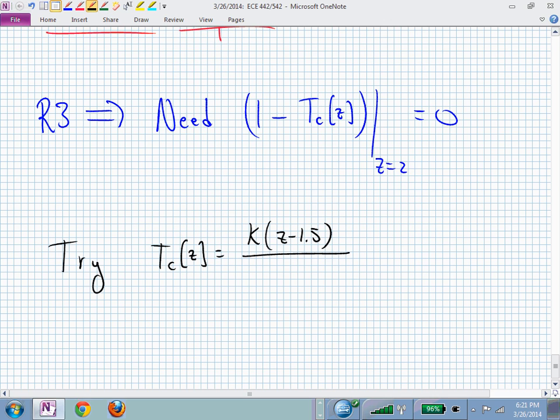How many do we need? 2, right? We need 2 poles because we need a pole zero excess of 1. We need at least 2. And if we want the smallest complexity of our system, let's just stick with 2. We could make it 3. Then our pole zero excess would be 2, which is bigger than 1, right? We need 1 or bigger for our pole zero excess because g of z had a pole zero excess of 1. Is that clear?